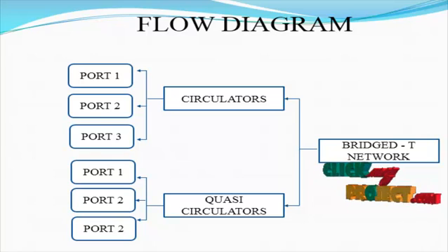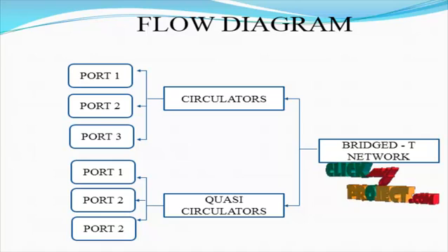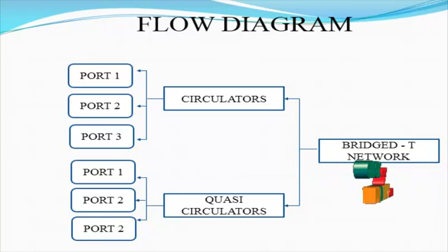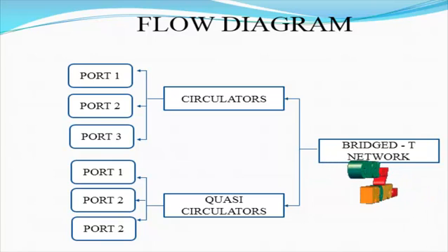The 3-port unit cell for an n-port circulator and its scattering parameters. Each port is assumed to be perfectly matched. BTN uses a signal cancellation technique and a band reject characteristic to reject S31. Both QC and BTN utilize the inherent non-reciprocity of transistors to suppress S31, and small values of S13 are also assumed. Therefore, P1 and P3 are mutually isolated ports.